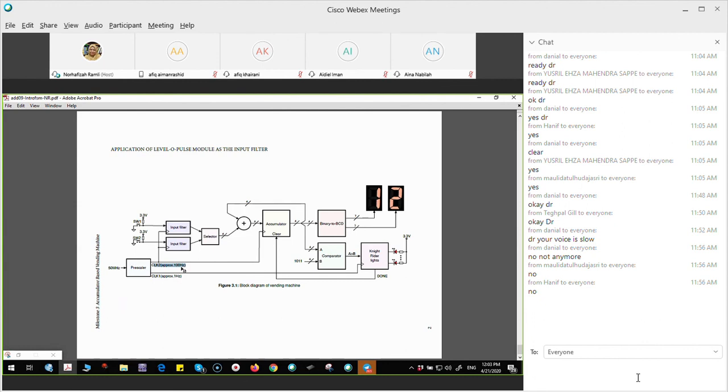Because as I'm speaking now, obviously I'm talking from one syllable to another syllable faster than 1 second. Same as your fingers. I think you can move your fingers faster than 1 second. That's why you put 100 hertz, which is 0.01 second. I don't think you can beat that 0.01 second, and therefore the input filter can capture that. That's why you change the frequency here, to pick up if you are too fast compared to the 1 hertz. But the rest of the clock here has to be 1 hertz.